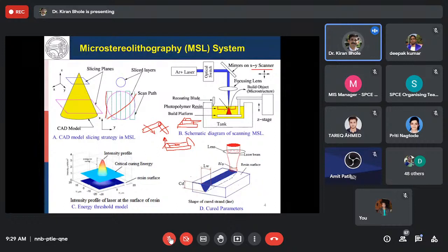But the very important problem is that when we have the resin between these two surfaces and we are curing it, it may happen that the cured structure also sticks to the top surface. Ideally the cured structure should not stick to the top surface, right? It should be free from detachment. I mean, it should detach from the top surface and it should be attached to the bottom surface. With respect to time, that property of detachment will not exist, and thus it puts some limitation on the actual employment of the constant surface.